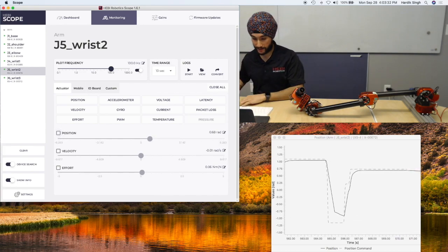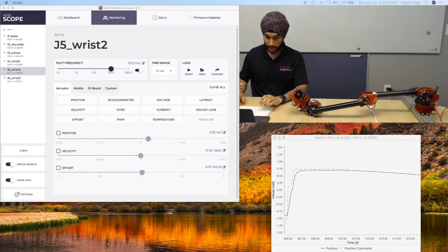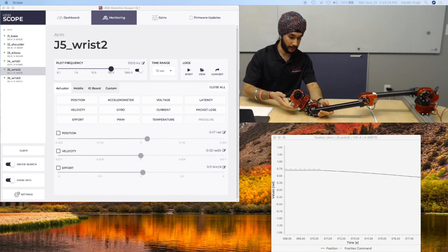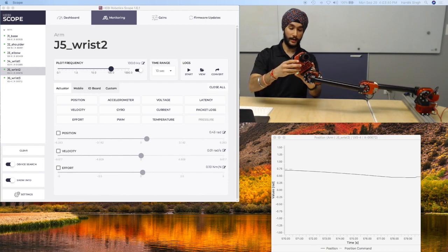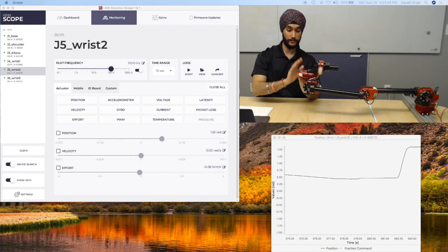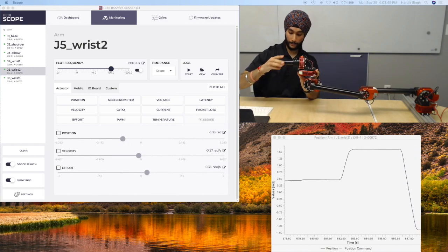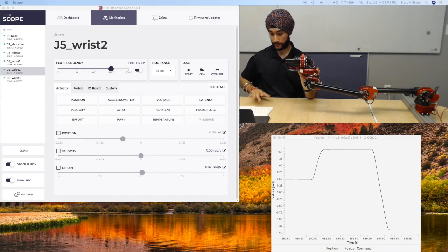So what I'm going to do now instead is run a little bit of code that's going to allow me to teach this arm a few positions. We were just moving this degree of freedom back and forth, right? So I'll do the same here with the trajectories. I'll set one waypoint right here. And I'll turn this around, and I'll set another waypoint right here.